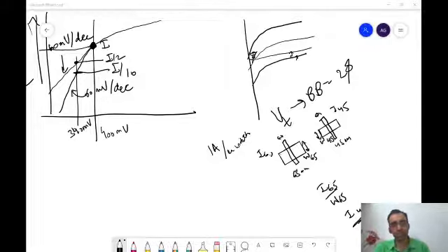But this definition assumes the scaling is happening as expected, right? In the previous lecture there was mention of the short channel effect. Won't it interfere here? Yes. VT shifts and then you have to recover it. You have to do device engineering so that you recover it. That you anyway have to do.